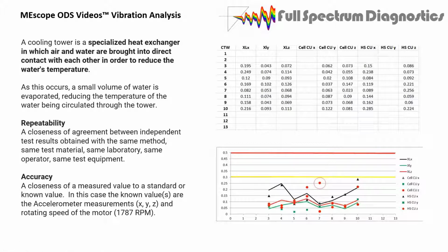Now, what I would recommend, if you're out there and you've wondered about the precision, the repeatability, the accuracy, put a transducer on there. If you have walk around data collection, you can put a transducer on your machine, take the data, and then go take a video and leave the transducer on there. Now you have a reference point, and you select a pixel on the screen that's on the transducer, and it should give you an amplitude in 2 different directions that are close to what you've measured, okay? And we'll show you how I did it, and you can improve on the process if you want and let me know about it, but that's what we're gonna do.